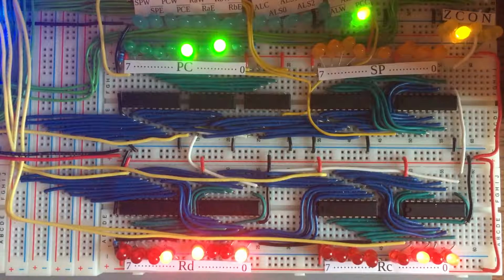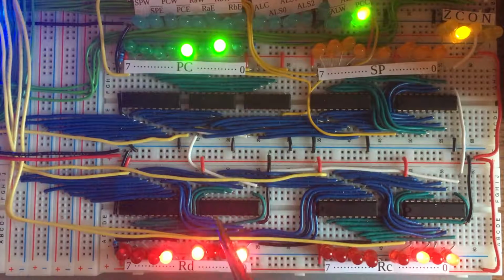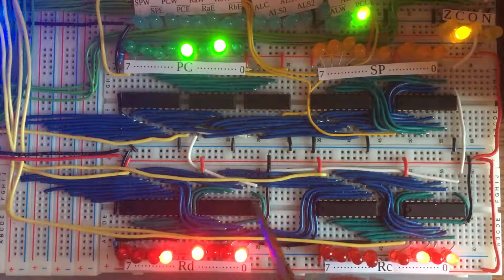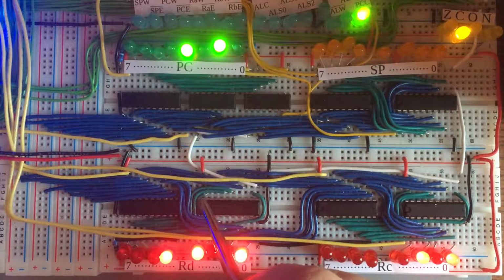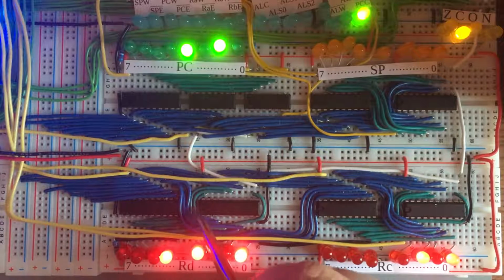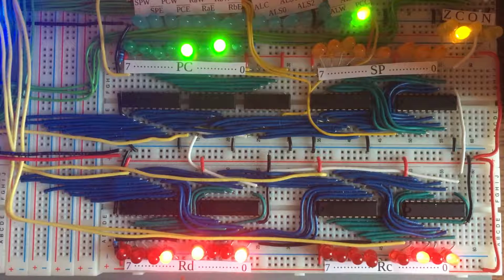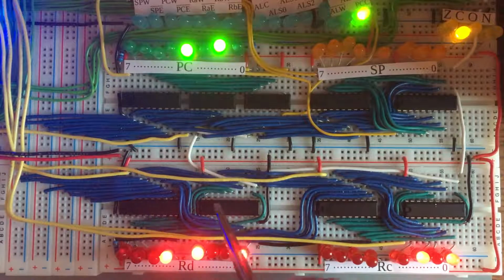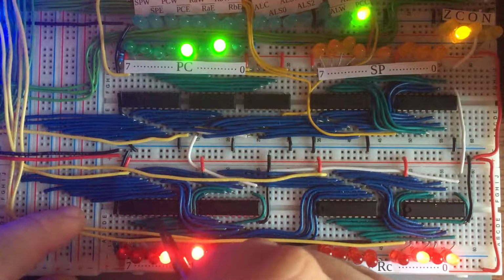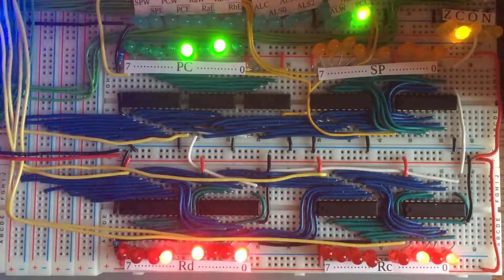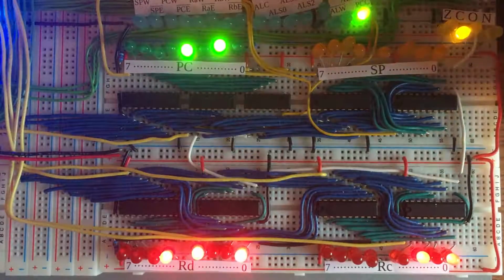And so those values are output on the various Q pins, and that's these green wires. The way we can actually tell the D register to output its value to other components on the bus is through this first chip here, the buffer. These green wires are all connected to the 8 pins on the bottom of this chip. And let's have a look at its datasheet.